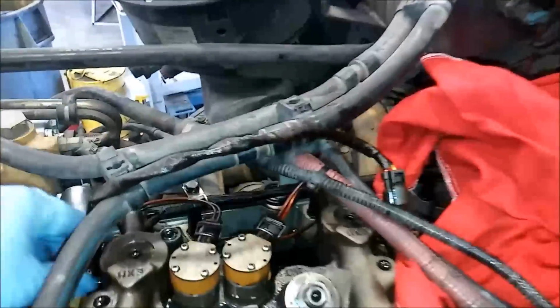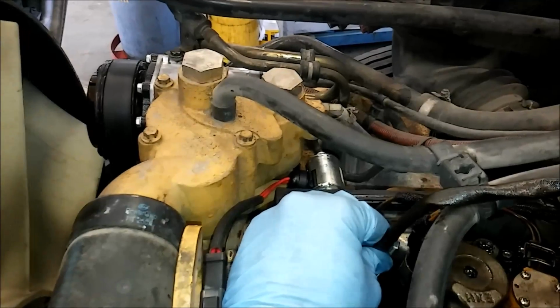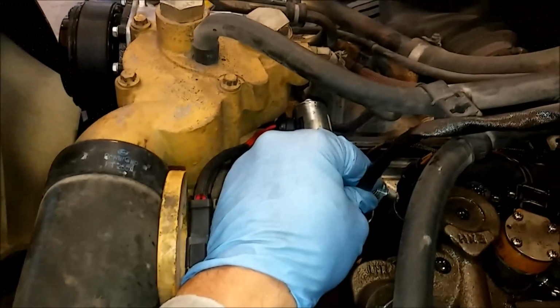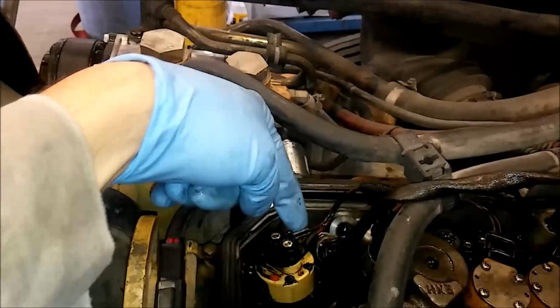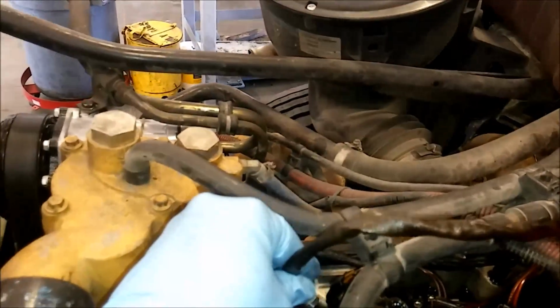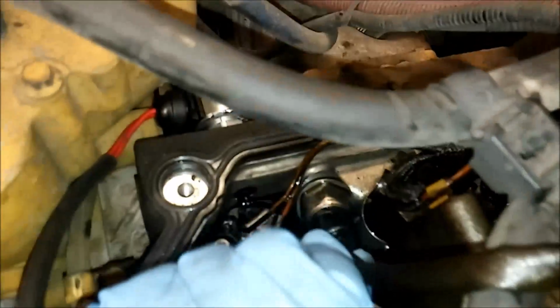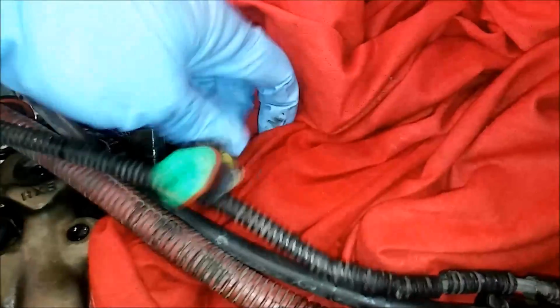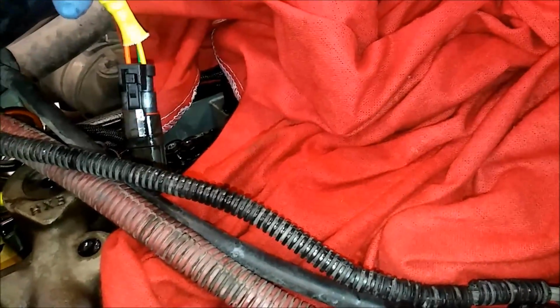Alright, so let's get back to troubleshooting. So we have a C13 here, and here is our IVA oil pressure sensor. It sits by cylinder 1, and it's under the valve cover, so it's going to be oil soaked. It's a 3-wire circuit. See it right there. And it's a 3-wire sensor. We're going to unplug it. And as most mechanics do, just get a new sensor. And we're just going to plug a new sensor in, and we're not going to do any troubleshooting or anything. This is going to fix this right up, isn't it?